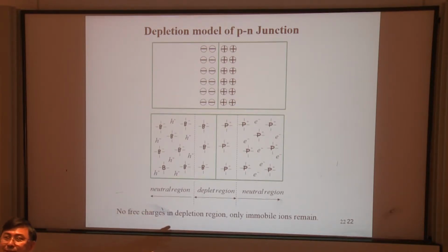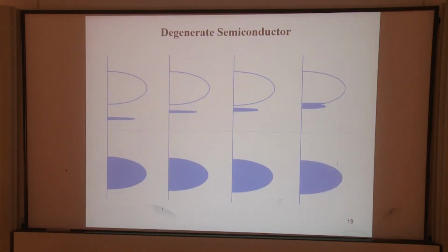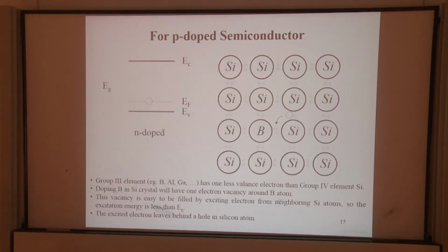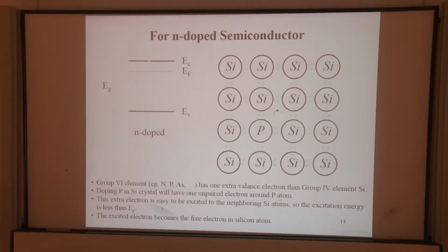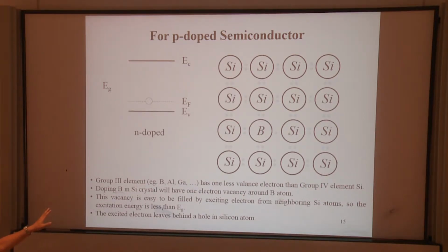Okay, so you have to take a look at yesterday's handout. You see? This is N-doped. I'm sorry, I may have put it wrong. This should be P-type. All right? So correct your notes on page 15. This is P-type. I may have misled you, sorry. For a semiconductor that is doped with a group 5 element, that will be N-type. But for silicon, if we dope with an element in group 3, then it will be P-type. I'll change that to P-type. So the Fermi level will be very close to the valence band edge.